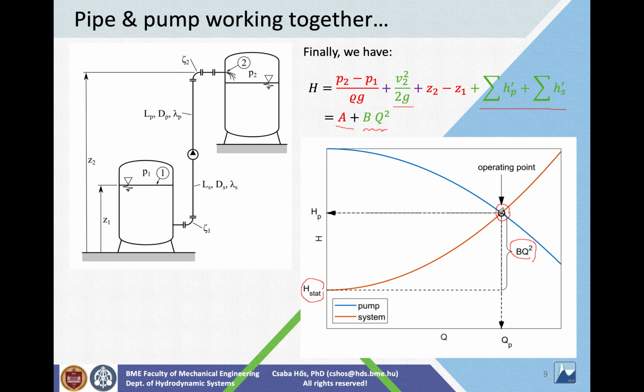So this figure simply means that if I plug this blue pump to this red pipeline, then this will be the flow rate. If I buy a smaller pump, whose characteristic curve is like this, then with this smaller pump and the same pipeline system, I'll have a smaller flow rate. And vice versa if the pump is larger.